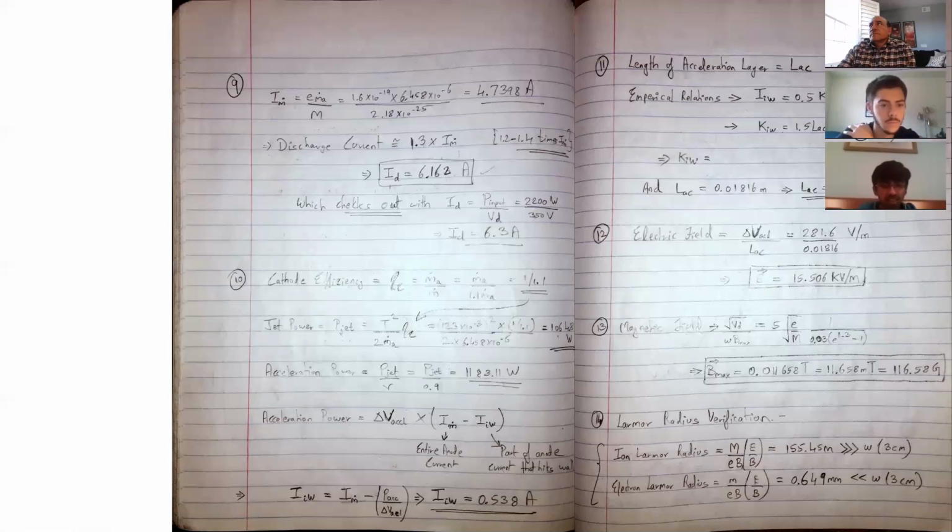So we plug in that voltage, which is responsible for accelerating these ions, times the current. And the current, as I mentioned, is not the total current coming out of the anode. It's the current coming out of the anode minus the amount that's lost into the wall. If we plug everything in, the only unknown variable is the current going into the wall, which we find out to be half an amp.